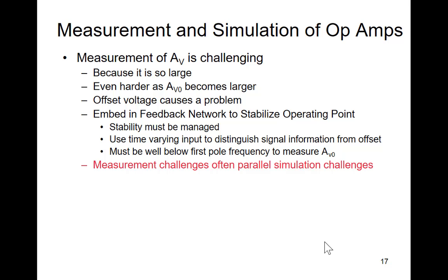Both of those amplifiers have a better bandwidth, and you cascade those 2 amplifiers together to get your gain of 100. So we typically don't try to make that pole of the op amp go out because we don't know how to do it. But we will look at a different system configuration where we'll cascade lower gain stages together to get our gain up. Make sense?